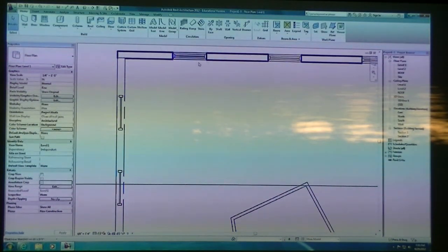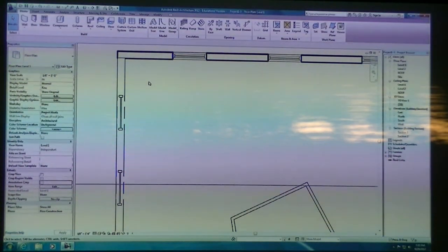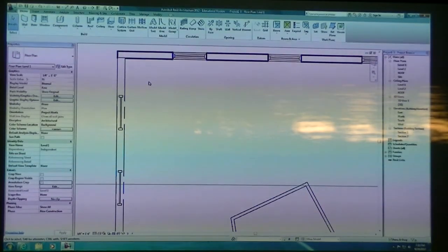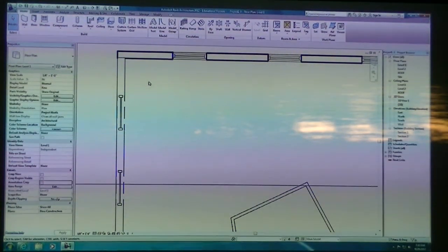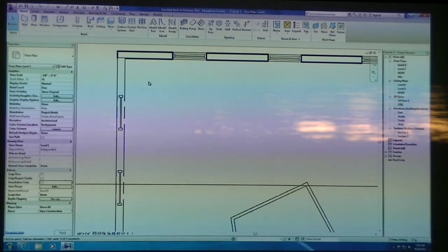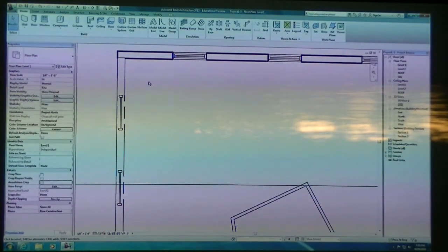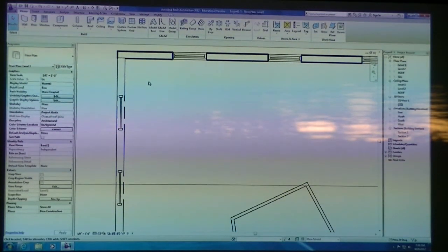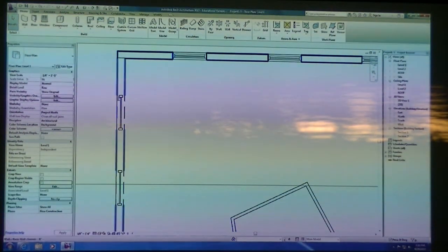It grays out and my new stuff is a lot darker. So by default it already kind of goes into the typical nomenclature and drawing techniques of what you would find if you're drawing something in CAD. Normally you would take your existing lines and make them really grayed out and light, and all of your new items are usually dark and a lot more solid and bold.